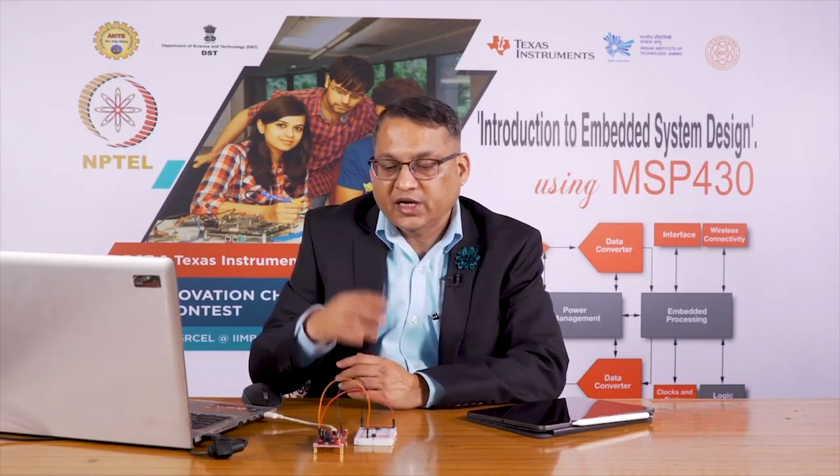So, I recommend that you play with all these 4 versions of the program. In the first version there is no debouncing, and you should be able to see that there is false toggling. It can improve when you connect an external capacitor of 0.1 microfarad, and then the rest of the programs are all going to debounce the switch. The second version of the program uses the onboard switch, and the third and fourth versions of the program use an external switch with internal pull up or pull down resistor, as the case is in both these versions.